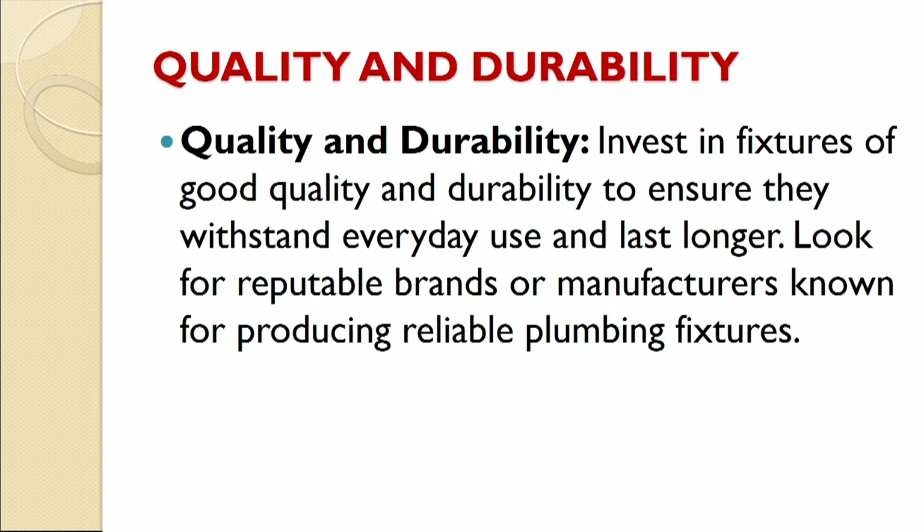Another thing is that if you are a skilled plumber, then you know many things about the different points you have to consider before selecting a fixture. For example, I want to purchase a faucet, so I have to see whether there is some leakage, whether it is leak proof, or whether its threads are proper or not. So all these things we have to keep in our mind.